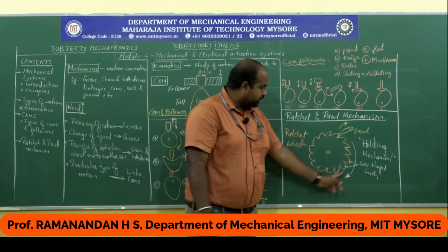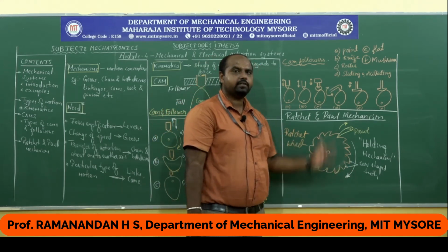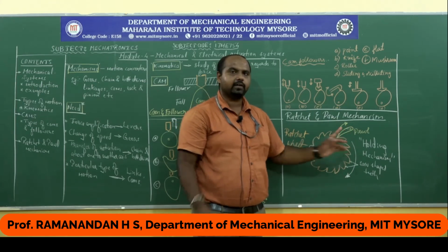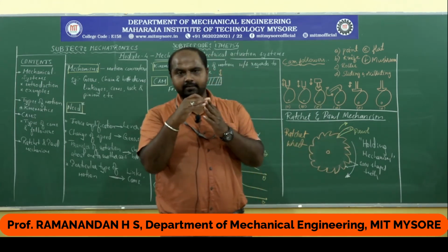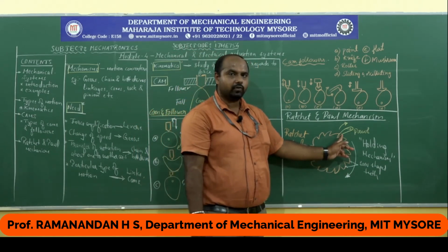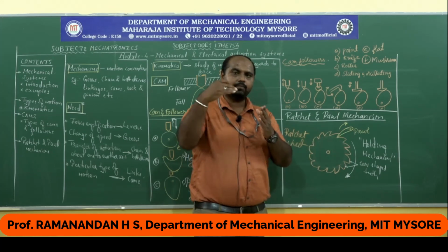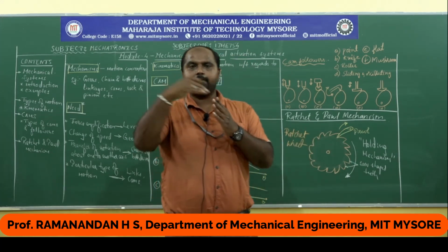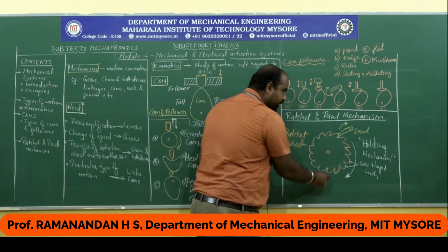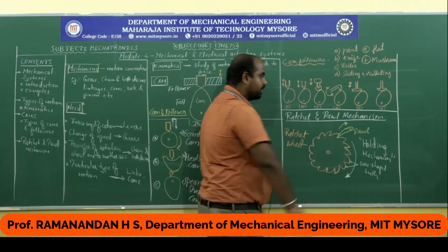Continuously the ratchet wheel cannot rotate in the clockwise direction because the pawl is holding at a particular reading. There should be a force which is more than the holding force. Then only the pawl will be pulled back, so that your ratchet wheel rotates clockwise, makes one rotation or a smaller bit of rotation.